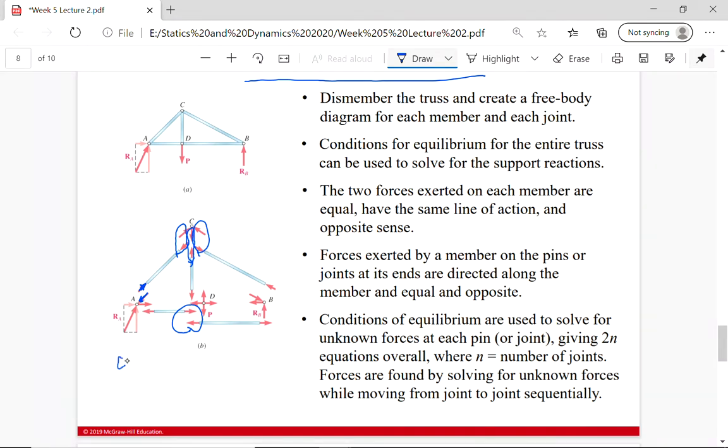So basically, I'll rewrite that. At joint A, I would do my sum of Fx forces and my sum of Fy forces. It wouldn't be super helpful to do a moment since all those forces would be acting at A. Then I'd go to joint B and C, sum of Fx and sum of Fy, with the idea that if I already solved for this force in reaction A, then I know this force, and therefore I know this force as well.